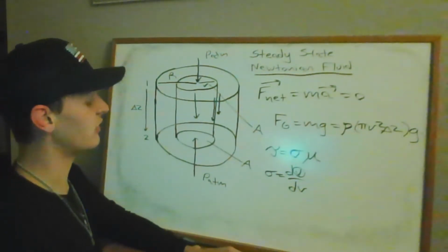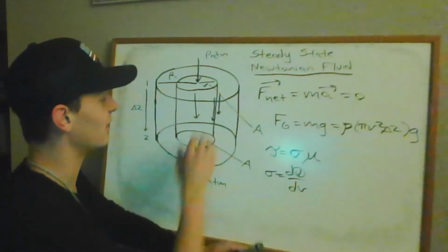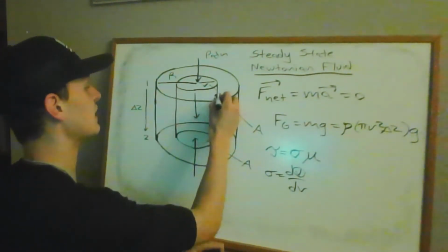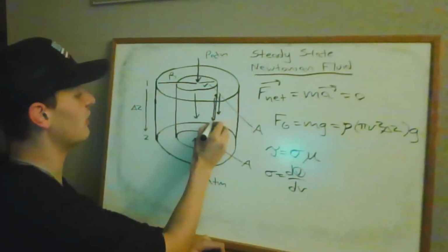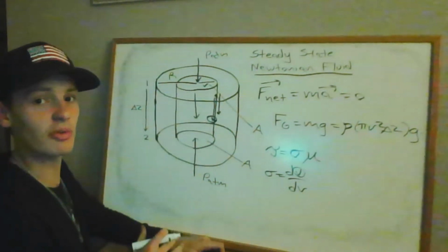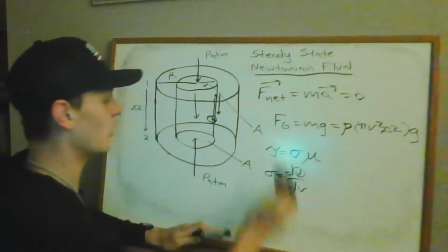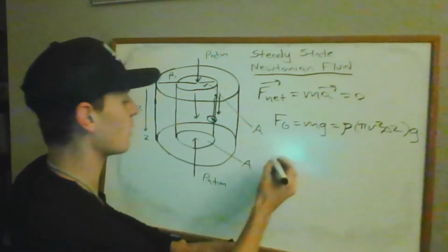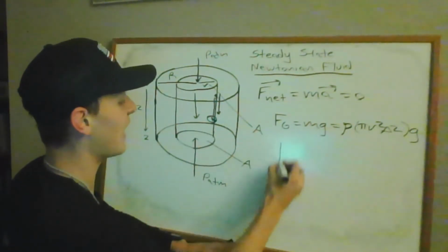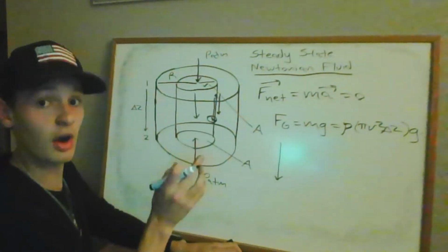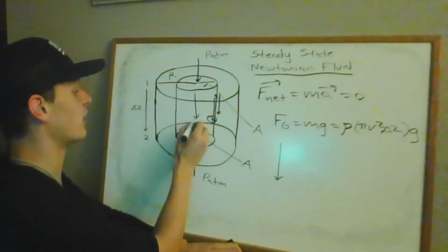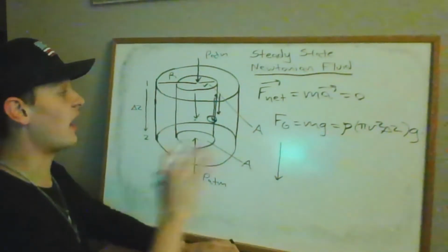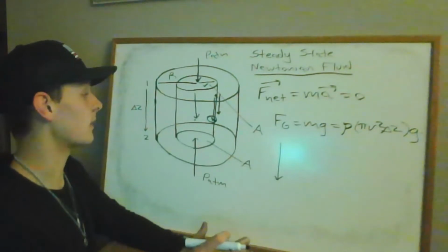Well, what that actually means here is that it's dragging, okay? It's exerting a shear force against the downward motion of the faster moving fluid inside our controlled volume. So that can be kind of confusing, right? So again, I'm going to repeat it one more time. We have fluid moving faster because it's at a smaller r, right? It's closer to the center here where r equals 0. Again, as we move radially outward, the velocity of the fluid decreases, okay?